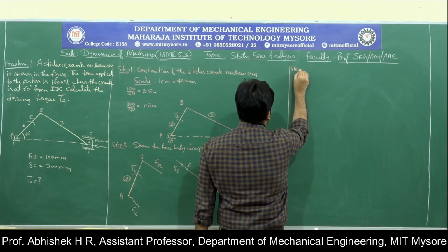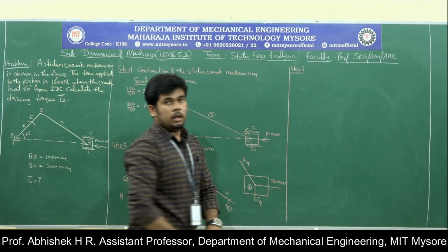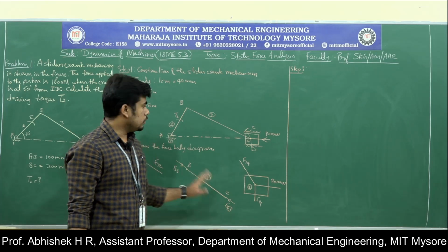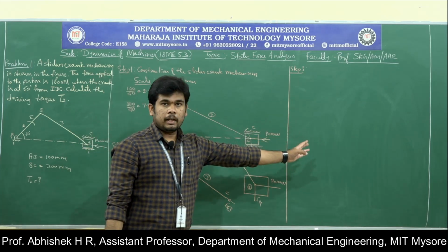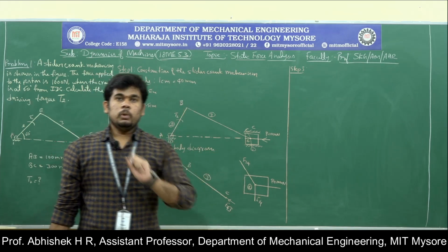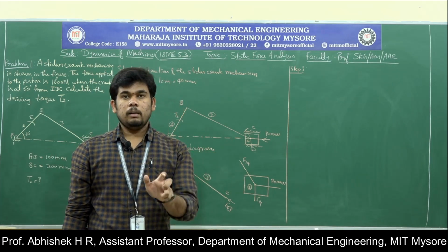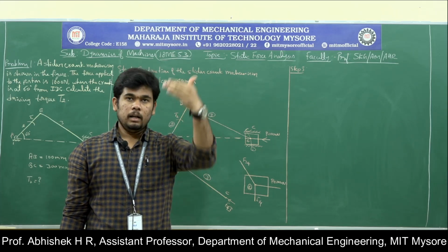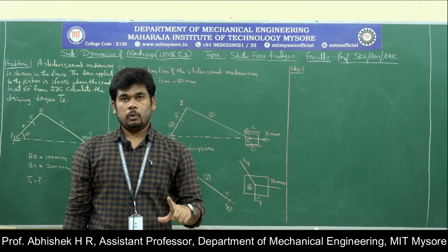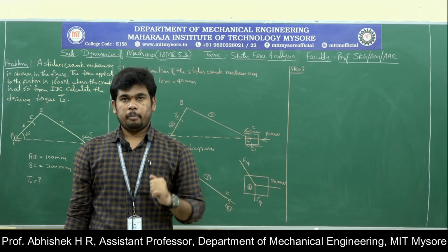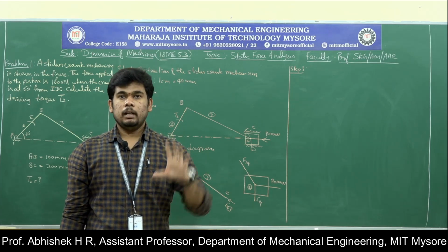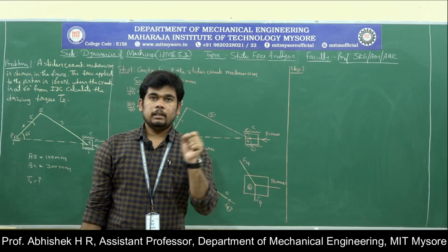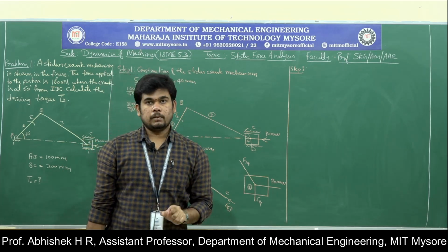Step 3. I will tell you one more thing. Here I don't have much space, so I will just continue in the next column. But while you are constructing on your page, start the mechanism at the top side of your page, and complete the entire problem on that single page only. Don't start the problem with half a page. Start with the full page and draw your mechanism at the top side of the page, so that it is easy to take the parallel line of the mechanism.